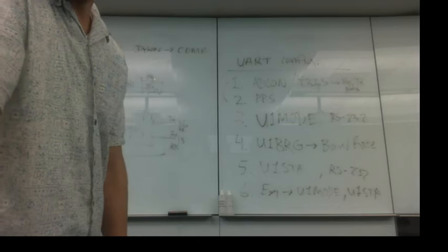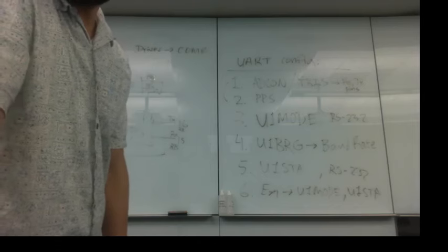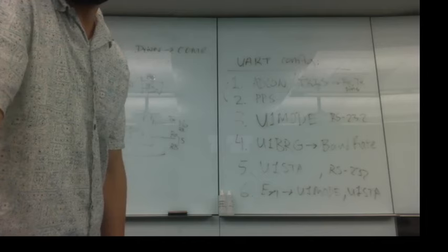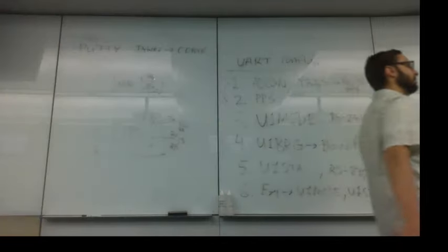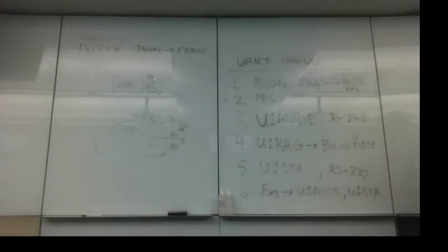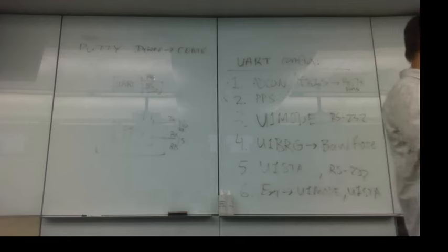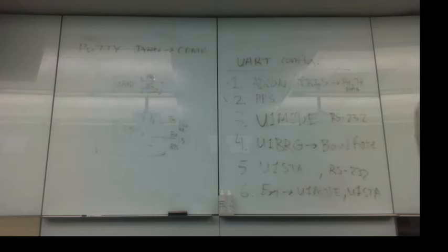You can do 0-1, which is interrupt generated when the last transmission is over, last character shifted out of the transmit shift register, and the transmit operations are completed. So that seems to be similar, but I believe the transmit shift register can store 16 bits, so it could store 2 characters. So it could shift 2 bytes in succession. So if you wrote 2 bytes to the transmit shift register at once, this interrupt would shift one out, or the interrupt would get generated when you shift both out.